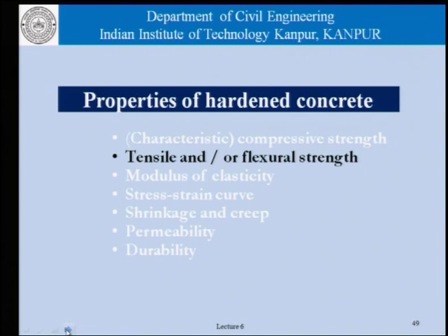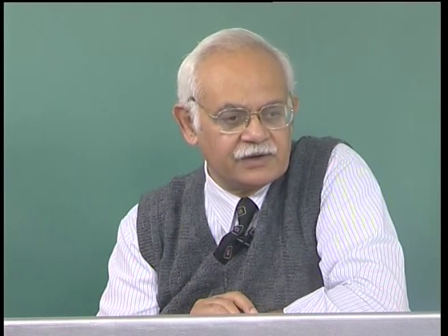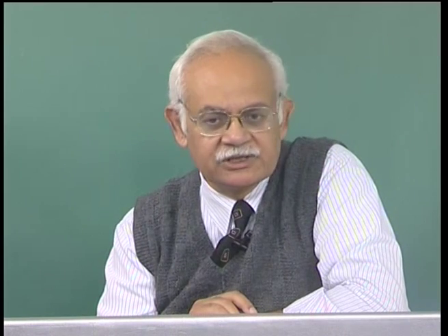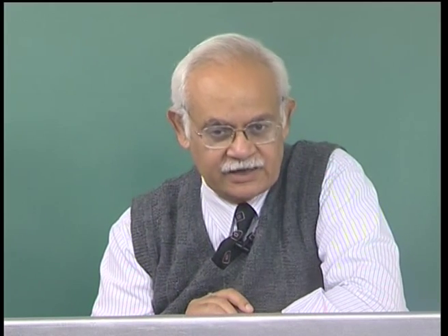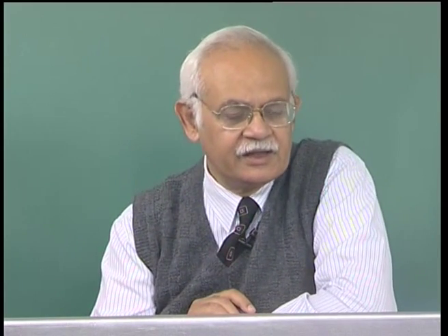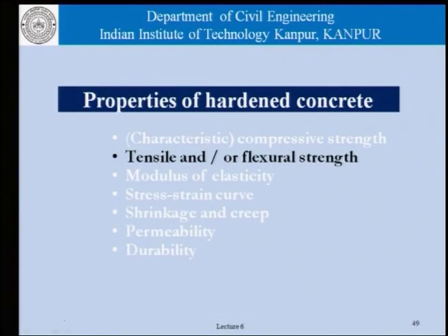Now, coming to tensile and flexural strengths, these strengths of concrete are often given in terms of the compressive strength. Codes may give expressions to enable a designer to estimate the tensile or the flexural strength. In certain cases it is these parameters that really govern the design, and that happens, for example, in road construction, repair works and all that.